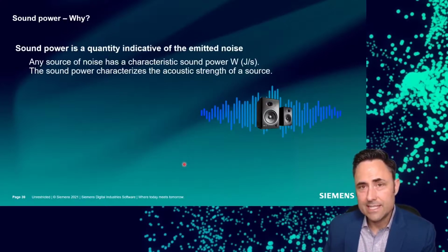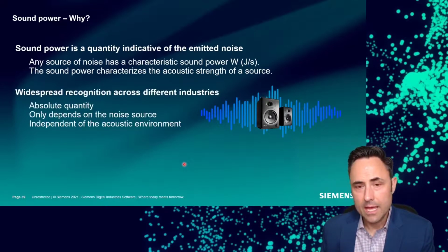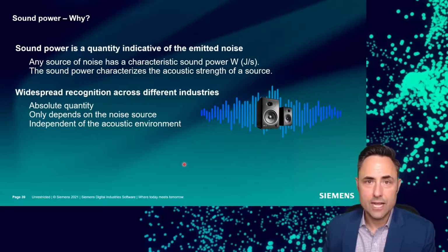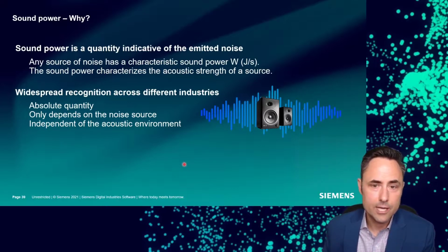And so it's indicative of the emitted noise for a given operating condition, regardless of how or where we measure it, okay? And it's useful because of this sort of objective nature of the sound power value. It's an absolute quantity. It only depends on the source itself and the operating condition. So if we turn it at 50% power versus maximum power, it's going to be a little bit different, but if we keep those things constant, we will get the same wattage, right?